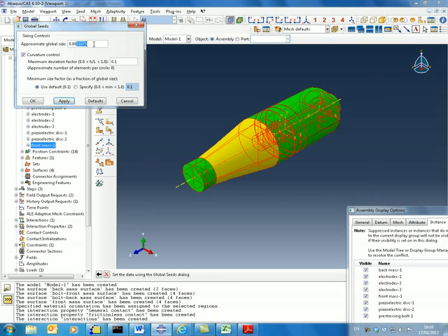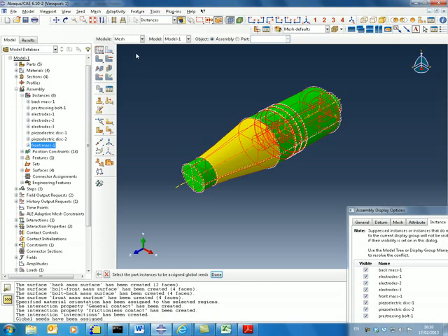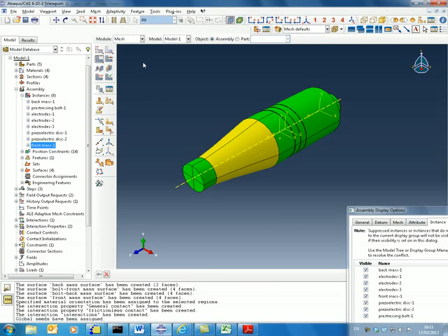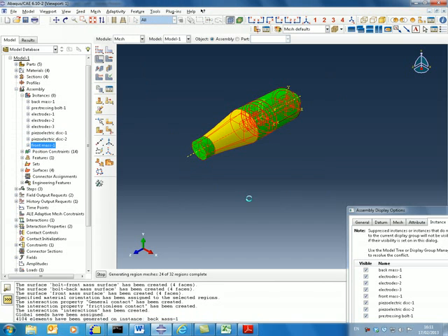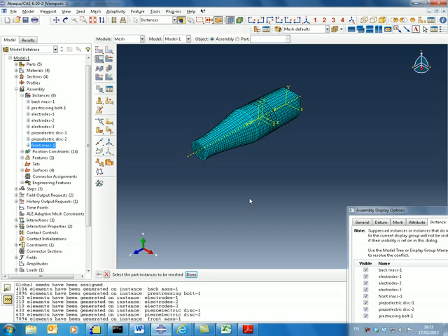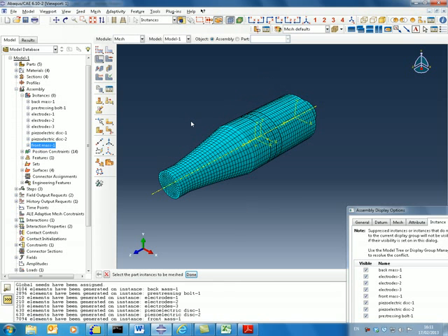At this point you can select different types of size and then run your model to compare the results you have got with the element size. This is what they call the mesh convergence test. In this model I've just used 0.002 and then mesh the part. I select all the parts and generate a tie constraint across the incompatible interfaces. Now the model has been meshed.